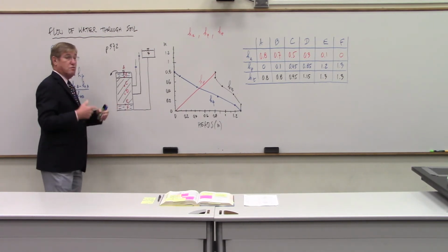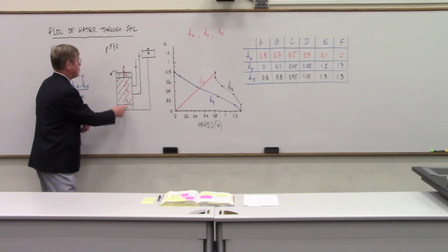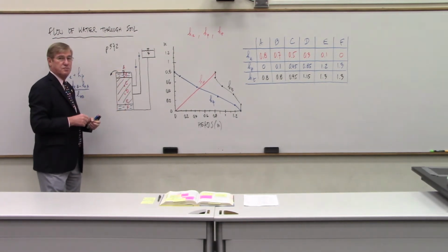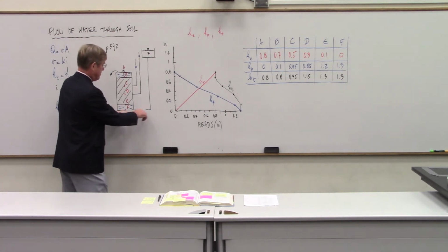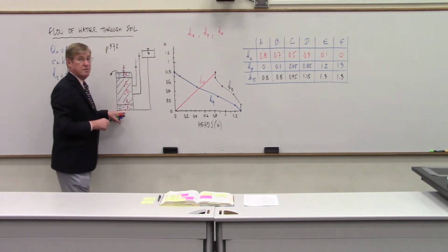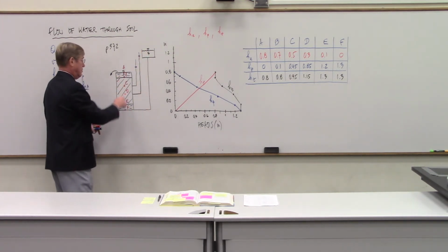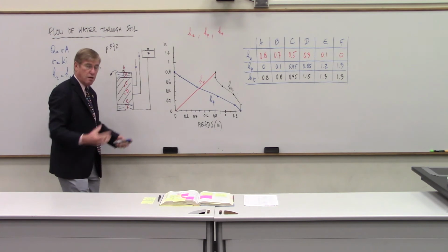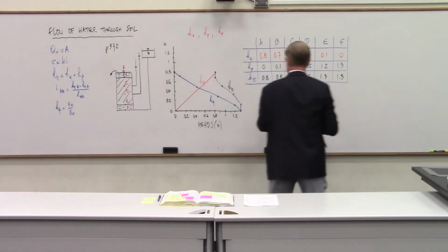Here we have hydrodynamic water pressure, and you cannot go distance from F to A times gamma W. You have to find a clear water path to a water level. That's why the pressure at F is this much and not that much, because the water loses a lot of energy to go through the soil.